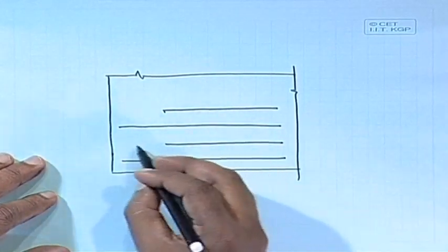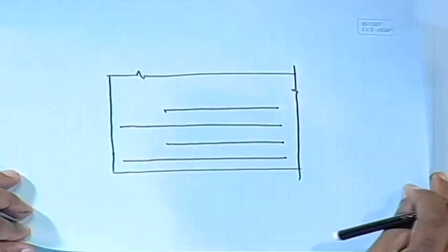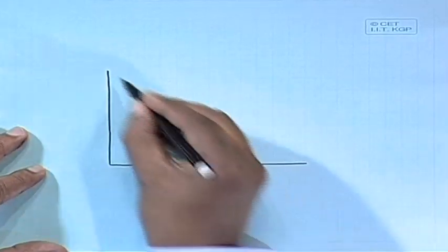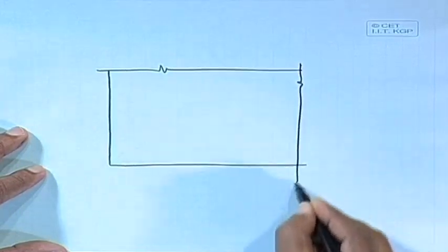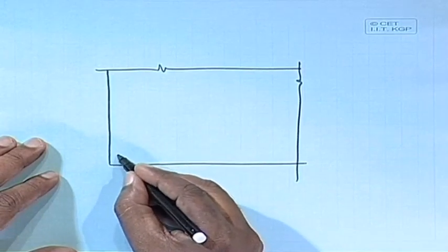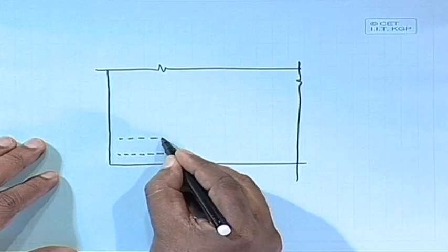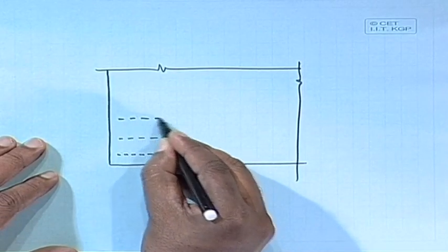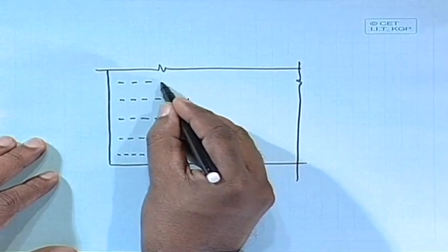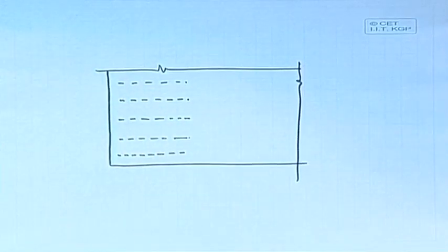So, if we do it, now what about the top one? The top bars here, say we have started, it will be dotted, the second one also will be dotted like that. These are all separate bars, and we follow this type of detailing nowadays. We do not go for that crank nowadays, and that way it is easy also. The top bars having separate spacing.